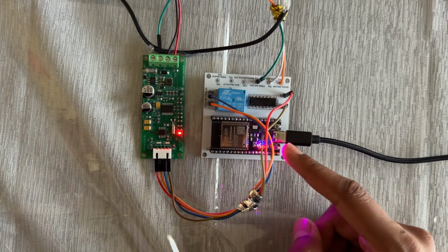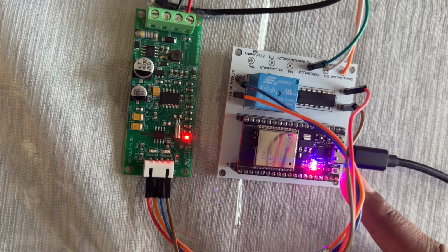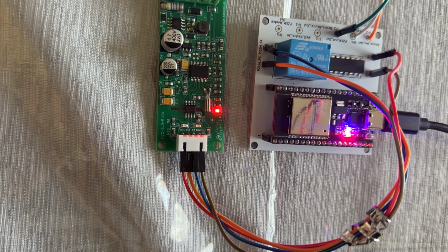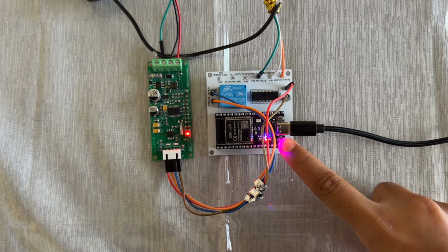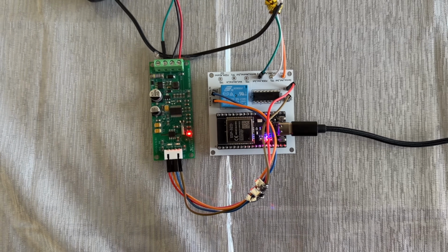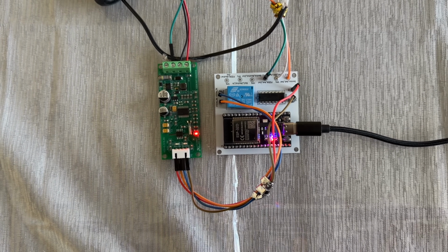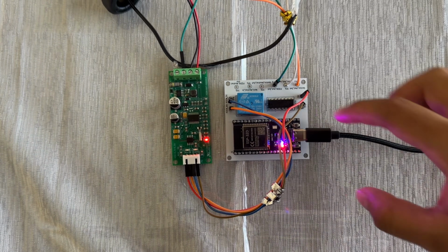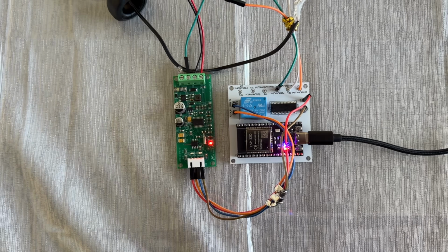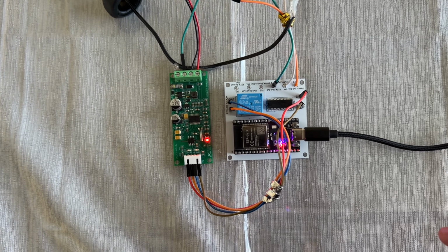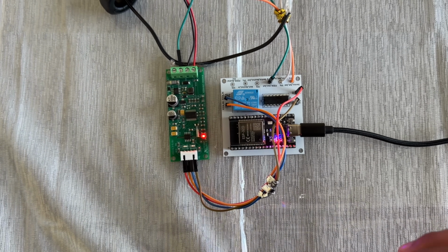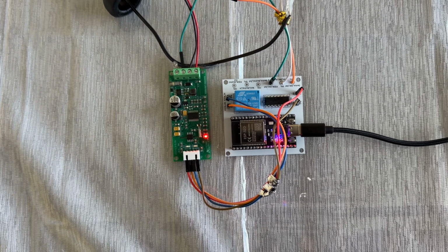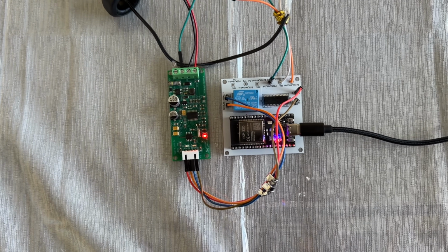So we also had a blue status LED, which tells us if Wi-Fi is connected or not, and then just UART status LEDs over here on the PZEM. The ESP32 will then communicate live readings to the locally hosted website built through its built-in Wi-Fi feature. Additionally, the ESP32 will control the state of the relay with the GPIO through the L293D. The relay could cause inductive currents, and it carries large voltages from the wall that could damage the microcontroller, which is why it is necessary to use a middleman like the L293D. For more information regarding specificities of components, wiring diagrams, or PCB designs, refer to the README.